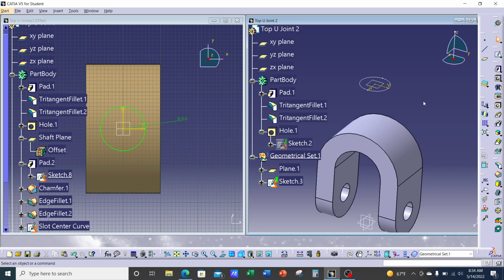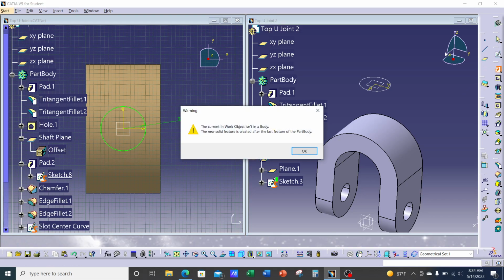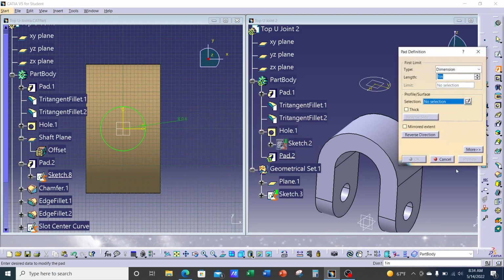Okay, so we're going to create a shaft. And anytime you use the extrude or pad command, it always goes perpendicular to the sketch. So obviously it's going to go in this direction, going upward, in the Z direction, right? Okay, so let's go ahead and create a pad. Oh, I completely forgot. Let me cancel.